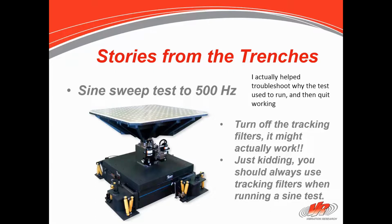They went back, and called me back a half hour later. Thank you so much. Yes, that was the problem. You solved it. We now can run our 500 hertz test. Everybody is happy. So I explained to the customer, well, you understand that with the tracking filters turned off, you're just measuring noise and assuming that that is the energy at that frequency, and it's not true. You are not testing it to 500 hertz.